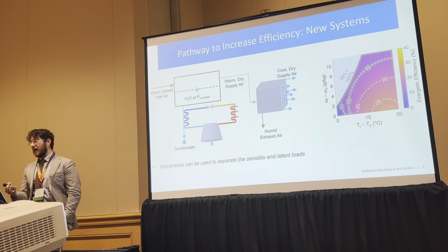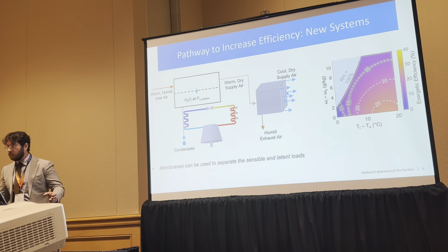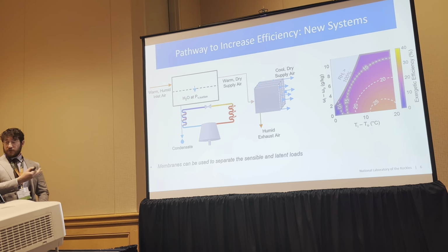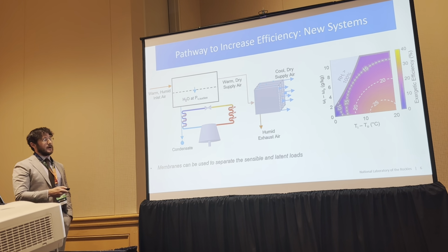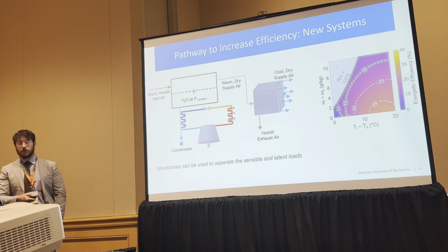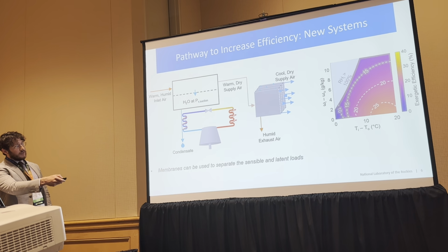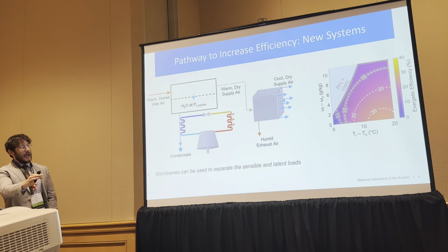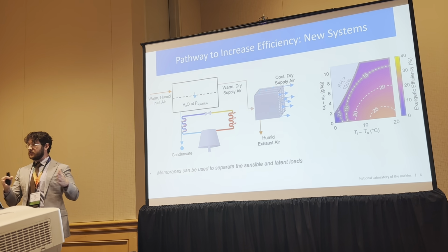So a normal evaporative cooler is called a swamp cooler because it's making the air more humid. Here we do it without making the air humid. And so that's a benefit of this dew point indirect evaporative cooler. And so you can see that this system is, again, more efficient than a conventional air conditioner. And it's actually more efficient than the desiccant system at these higher temperature lifts that we're trying to achieve.